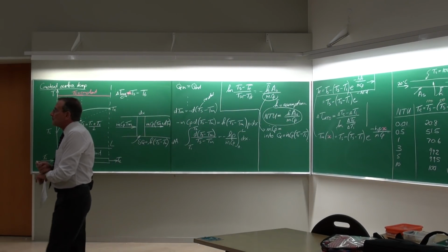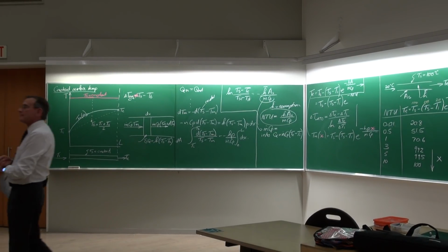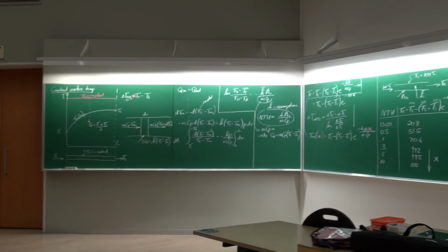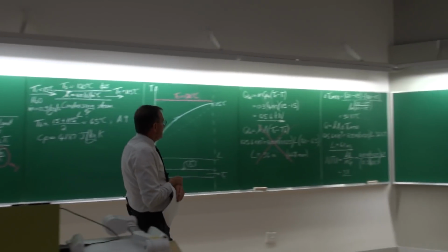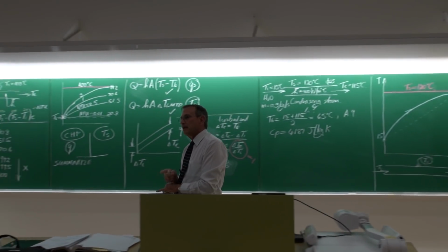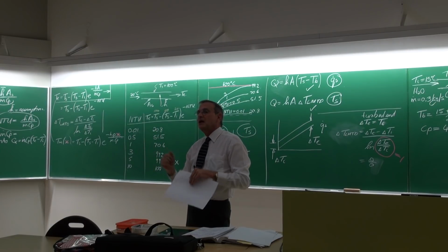Question? So you still evaluate the properties at the bulk temperature, but not the LMTD? No, you still calculate the properties at the bulk temperature, not the LMTD. What is the reason for that? The experiments have been done using that as the criteria.